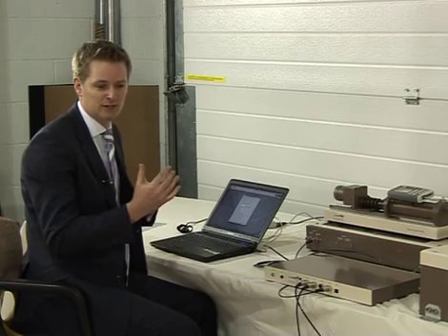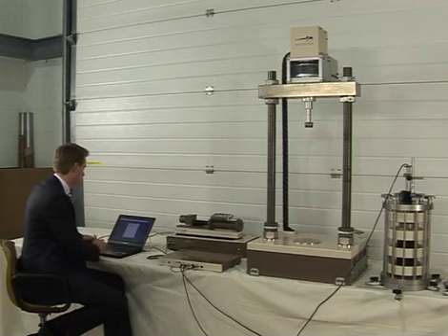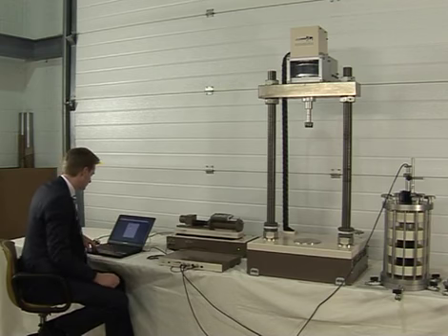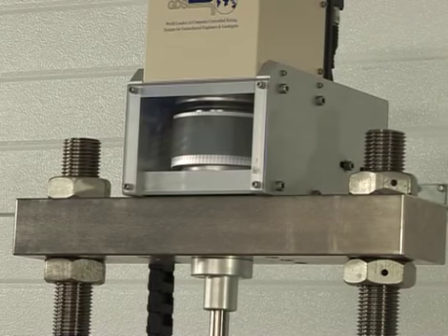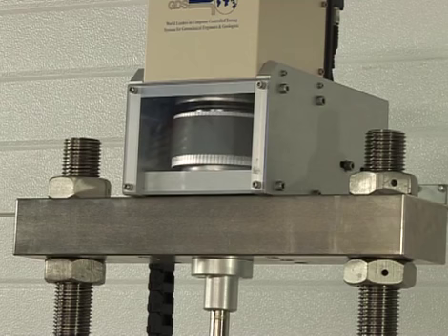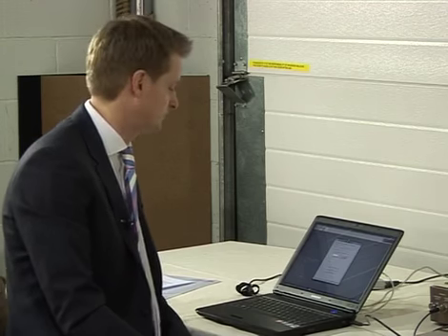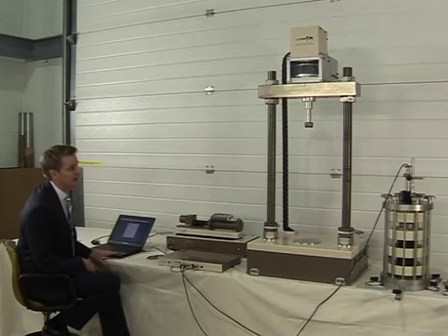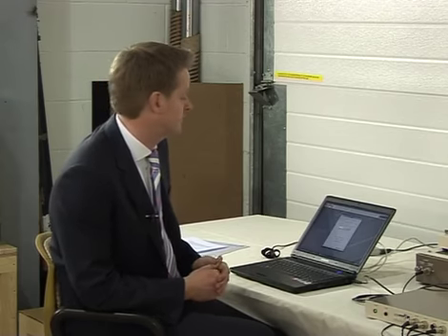But the nominal stroke is 100 millimeters, so first it needs to detect and calculate exactly what the full stroke is. So if I say set position, what it will attempt to do is go to the very top of its stroke, and then it will track down to the very bottom of its stroke. It can calculate the full stroke compared to its limits, and then move to a position 50% between those limits. It's good practice to know exactly where the RAM is in its stroke, and I thoroughly recommend we set the RAM to 50% of its full stroke before we proceed.